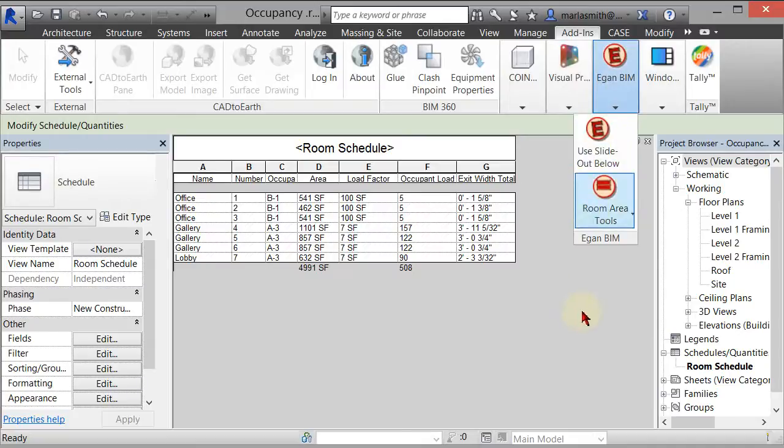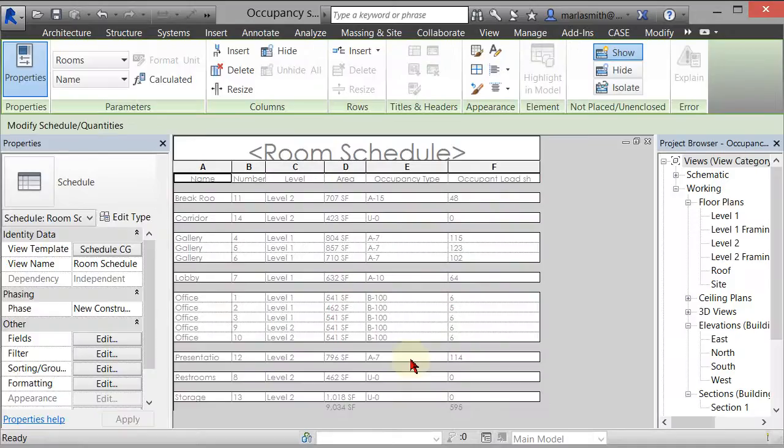and there's some information and tutorials out there on that if you would like to try that. What I'm going to do is, if I just Control Tab to this new file, we're going to create two shared parameters, an occupancy type and an occupancy load, and we are going to use Dynamo to access these parameters and do the calculations for us and then load that back into the project. So basically we're going to write a little script to do this for us.